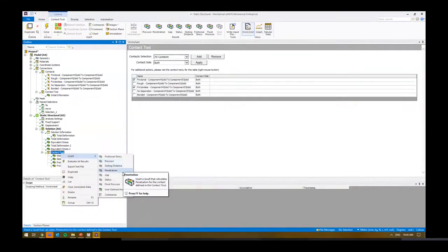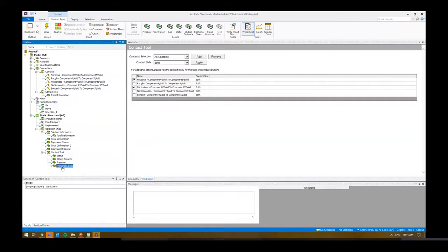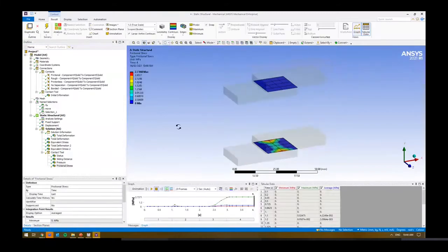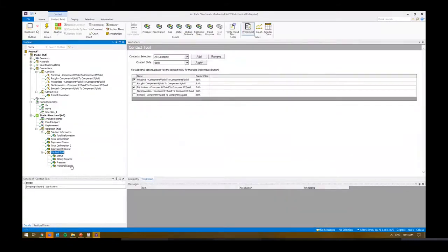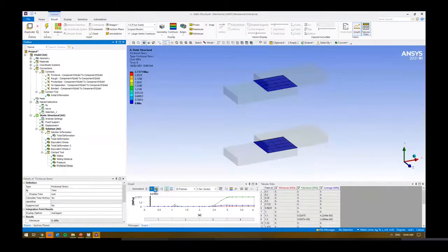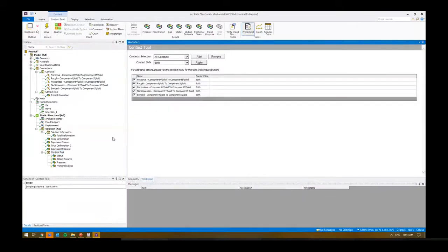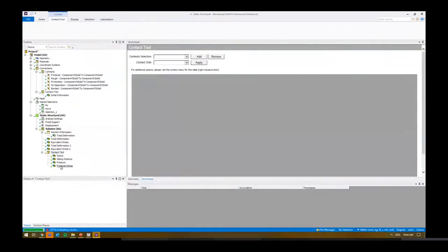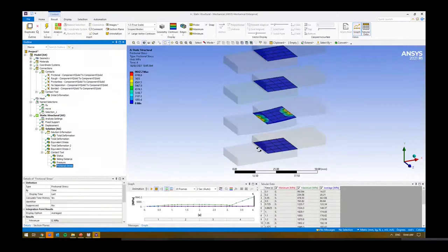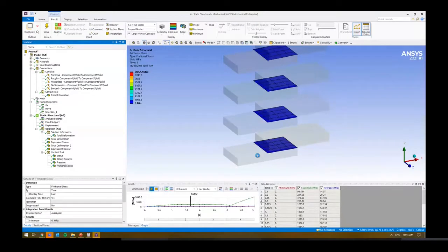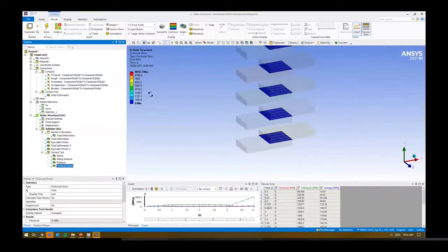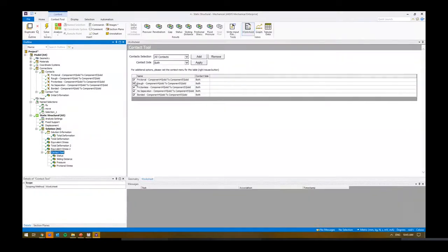And we'll notice as well, so we've got frictional stresses. We can also have a look at penetration status as well. We'll notice straight away that we only really have any frictional stresses on the component on the right at the very bottom, because we've got frictionless sliding at the top. And if we look at everything else, we'll reevaluate everything. And you'll notice again, it looks like we've got some frictional stresses on the rough, right? It's very large, but predominantly it's all